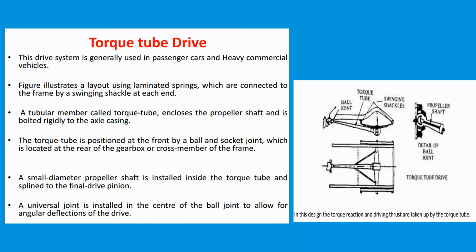The engineering problem that the torque tube solved is how to get the traction forces generated by the wheels to the car frame. The torque moving the wheel and axle in the forward direction is met with an equal and opposite reaction on the axle housing and differential, making the differential want to spin in the reverse direction, in the same way that a cyclist pops a wheelie, lifting the bicycle in the air in the opposite direction from the turn of the wheel.